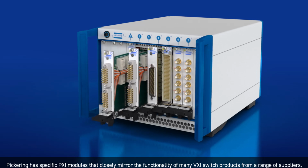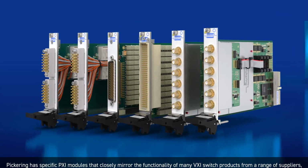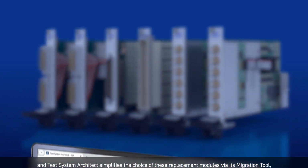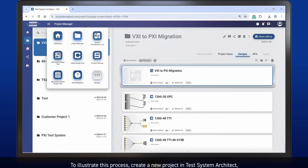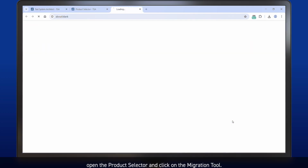Pickering has specific PXI modules that closely mirror the functionality of many VXI switch products from a range of suppliers, and Test System Architect simplifies the choice of these replacement modules via its migration tool, a subset of the product selector. To illustrate this process, create a new project in Test System Architect, open the product selector, and click on the migration tool.